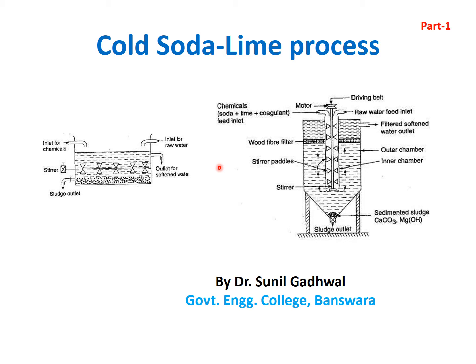For this purpose, a mixture of milk of lime, calcium hydroxide, and soda, Na2CO3, are added in a calculated amount from this inlet.